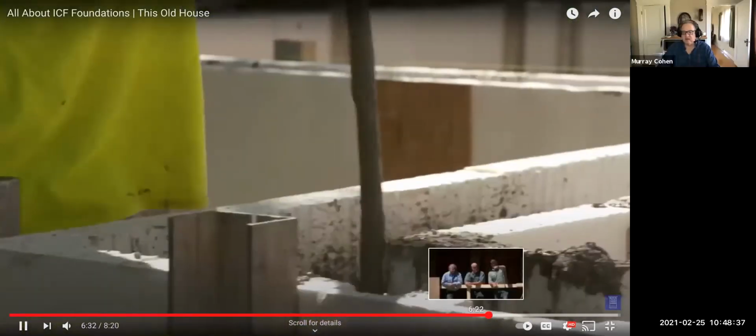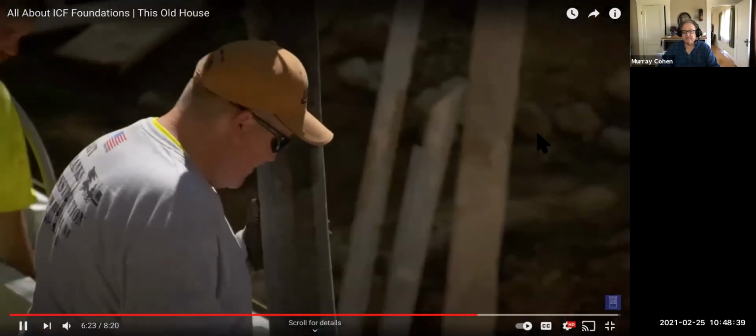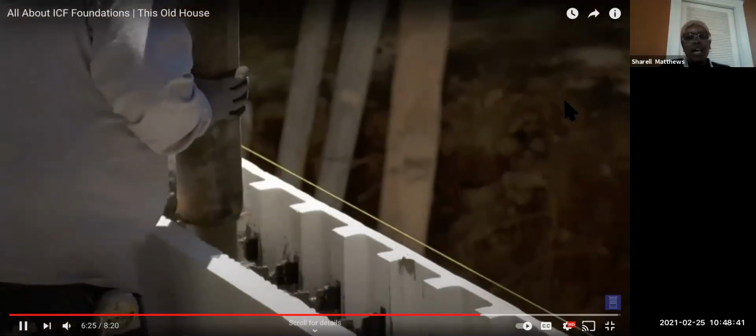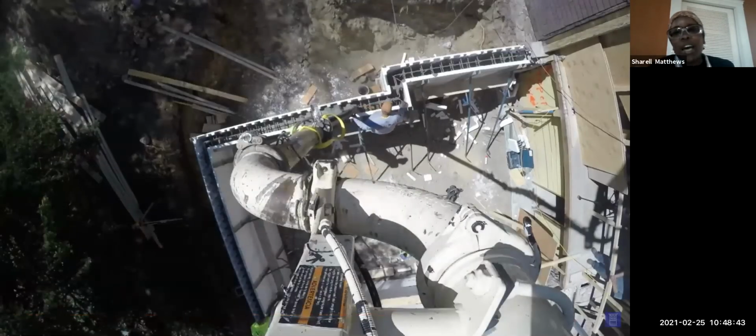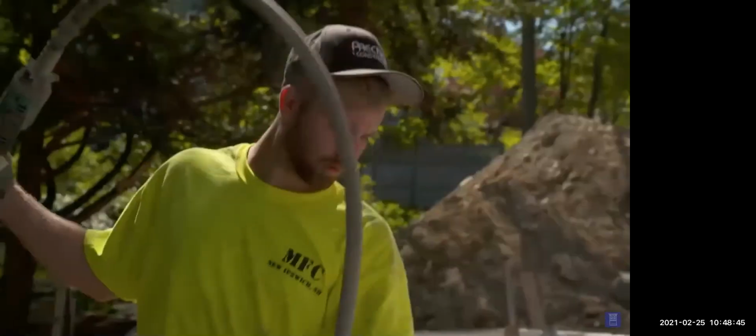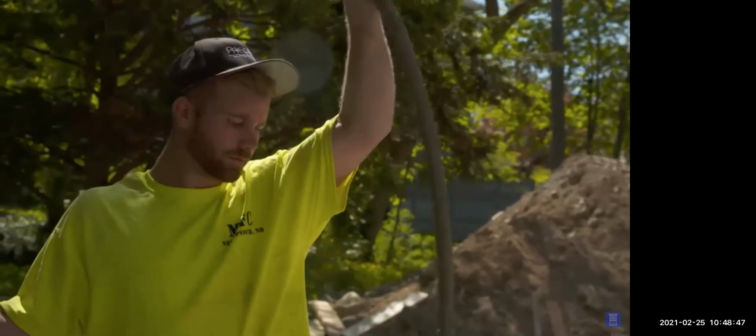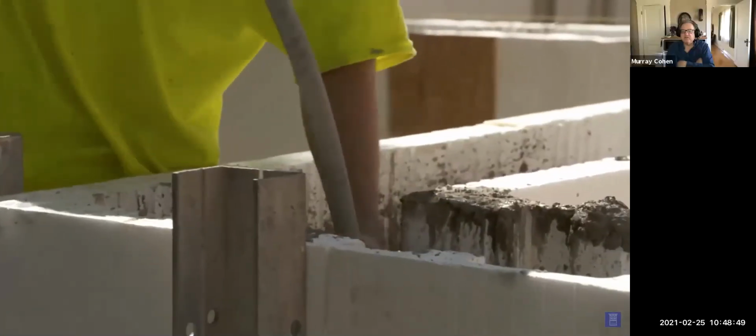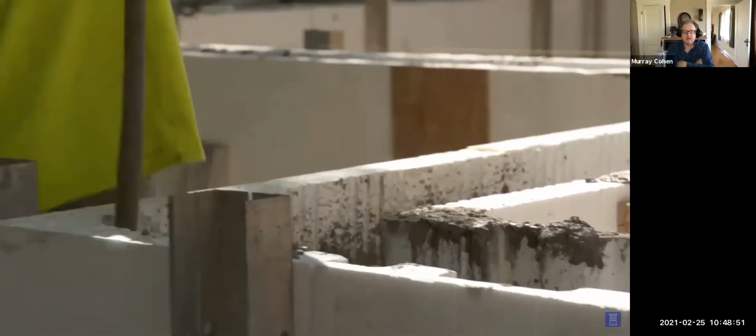Oh, here, I want to show you this part of it. Hold on. Well, we're going to place it in 4-foot lifts with the pump truck right in place. That's a lot of ties, though. You don't see that many ties on wood. Don't you have the rebar inside, right? Yeah, the rebar is just for tensile strength, though, not for the corners. That's just to keep the concrete from cracking and falling apart. But you need braces on the other side too, right? Well, on the left and right they do, but it's not...